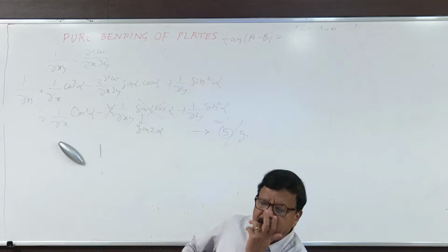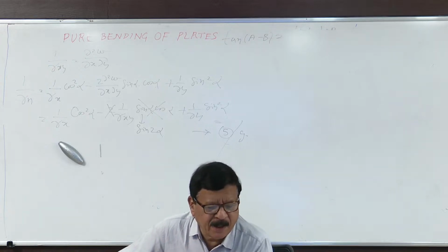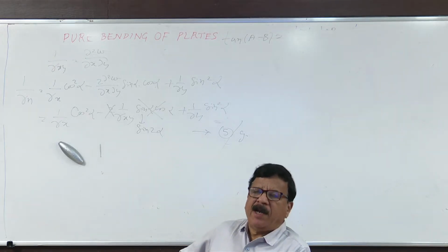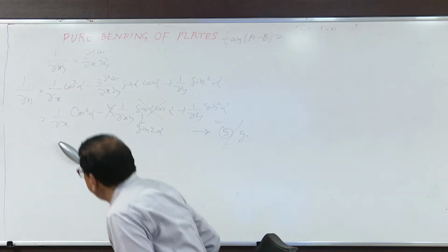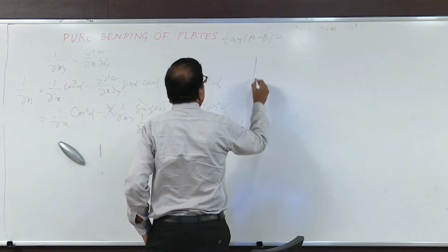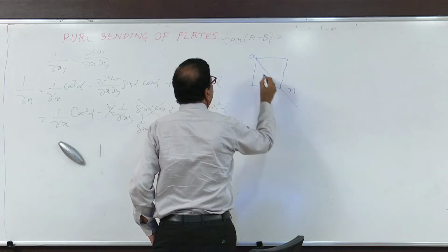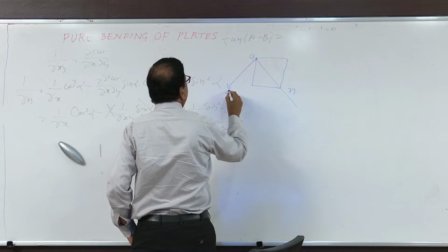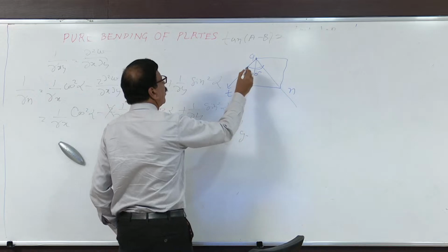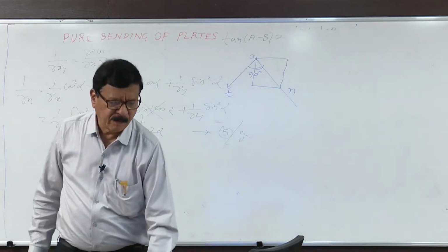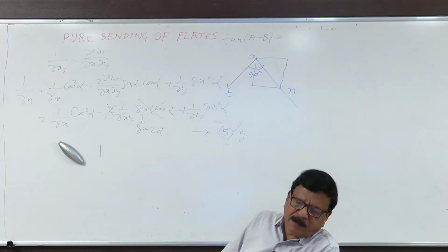Instead of direction AN we take the direction AT perpendicular to this, this was the AN. Now we took this AN rotated by 90 degrees, AT. There are always two principal planes, perpendicular to each other.